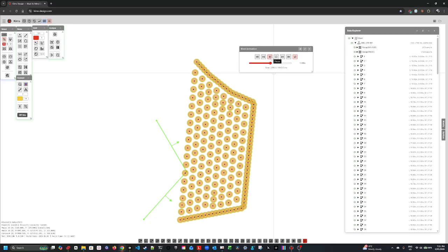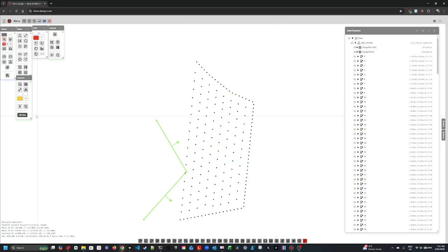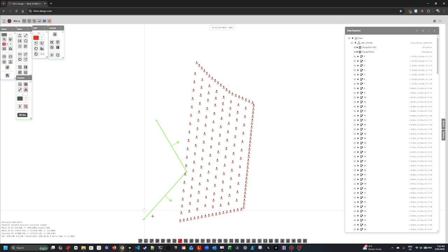Yeah, okay. Everything looks like it's in order. Good work, Brent and team. And then we need to tie it in, right? So we've got our harness wire here, there, we're going to select it. So we click on our harness wire, use our connector, and then we're going to, oh, my bad, tick that one too early. Go around this edge here.